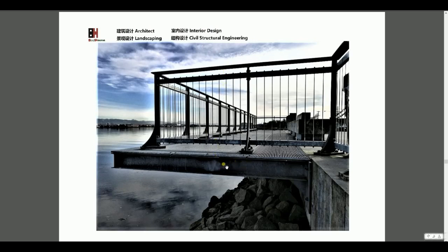Also, we can see the steel advantage is the size is small. For this kind of 10 feet projection cantilever, the size I think is less than 1 foot, right? It's probably 8 inches. So the 8-inch steel beam can cantilever 10 feet. Yeah, that's a steel advantage.